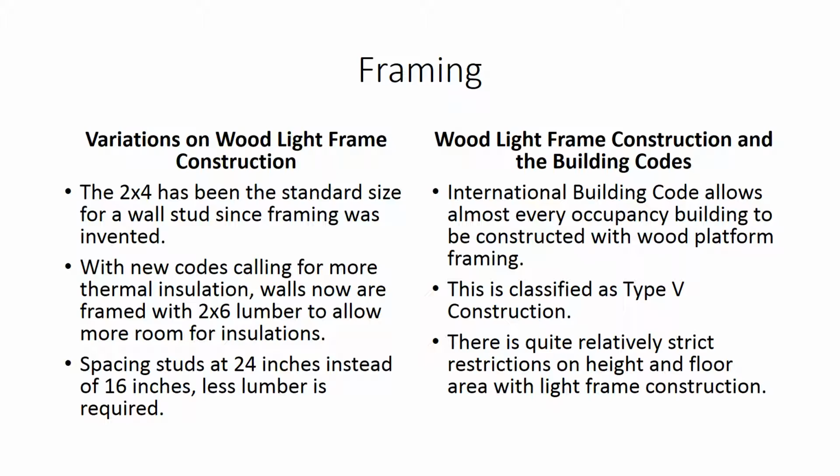The International Building Code allows almost every occupancy building to be constructed with wood flat platform framing. This is classified as Type 5 construction. There are relatively strict restrictions on height and floor area with light frame construction.